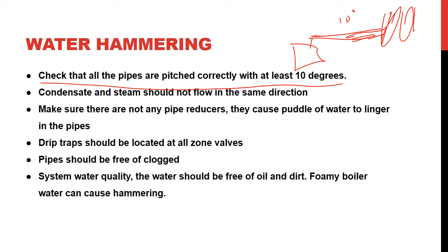Sometimes it's trial and error for pitching the pipe. You try it out, you pitch it, then you listen for the hammer, then you go again. There are a lot of variables that play into the water hammering issue: how insulated the pipe is, the temperature outside and in the room, the temperature of the steam. All these factors play into the pitching of the pipe. Most steam systems were installed a long time ago, but if you install a new pipe or a new section of a steam system, don't be frustrated if you don't get it right the first time. It is a lot of trial and error.